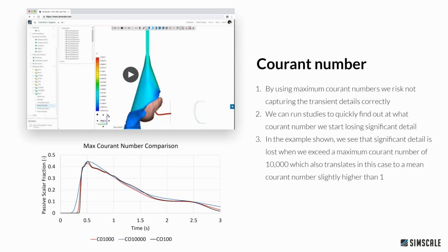So what you've actually got to do, if you're familiar with a mesh independence study, is do a set of results with different Courant numbers and see where you're going to start losing your detail, where you'll start to lose your accuracy.